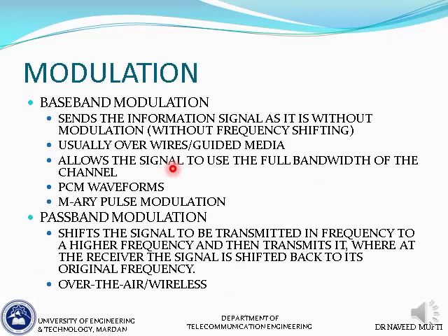A classic example of baseband modulation is the PCM waveform types we have studied, the line coding types, because if you remember, we are basically representing those bits by different pulses, and if you pick any pulse, the bandwidth requirements of pulses are very similar. So we don't really have a major frequency shifting when we change from one pulse form to the other.